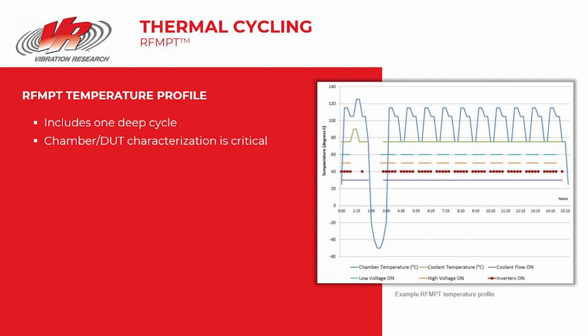Thermal characterization of test article ramp rates versus the thermal chamber is essential for verifying that the chamber is optimized for all test part locations and that true thermal cycling can be related to the correlated damage model. This is especially true if your product has any solder joints that are being tested. We want to make sure that the part itself is seeing the delta T's that we are prescribing.